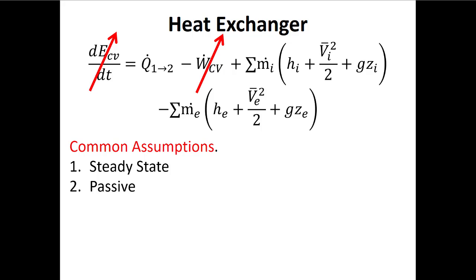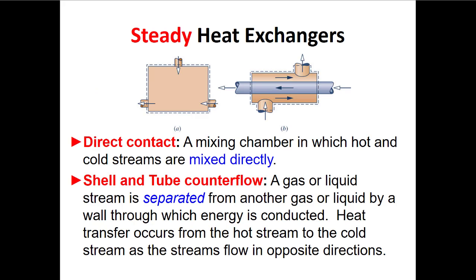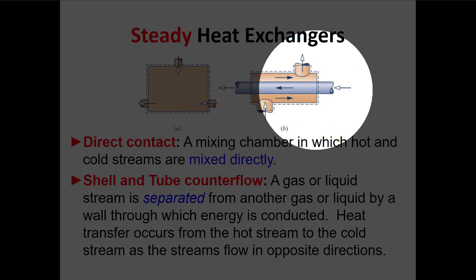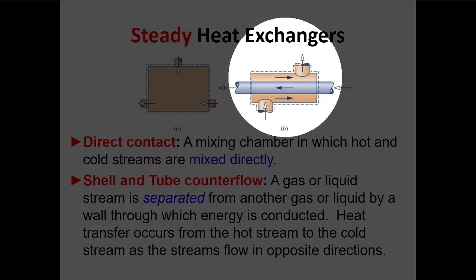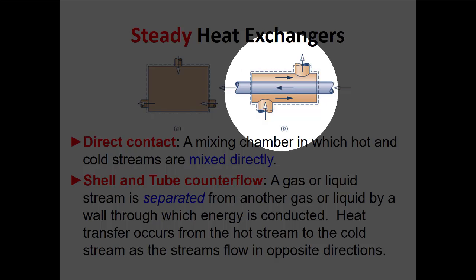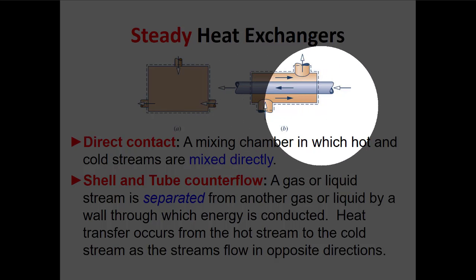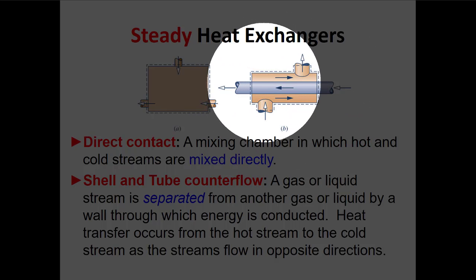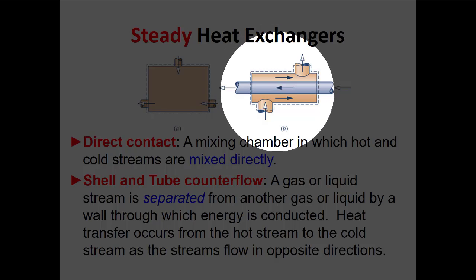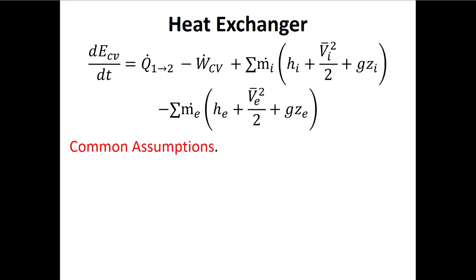But if I'm thinking about the whole heat exchanger, so here, say my hot fluid is in the tube and my cold fluid is in the shell. I'm definitely going to get heat transfer between the hot fluid and the cold fluid. But if the whole system is adiabatic, right? So if I wrap this whole heat exchanger in lots of insulation, so it's really, really well insulated, what this means, if it's adiabatic, is that all the heat from the hot side goes into the cold side, right?